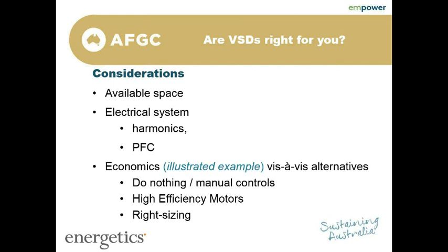If you're quite restricted on floor plate for your site, they do take up a little bit of room, so making sure that there's room for them to be installed. Another thing to consider with the available space is the temperature. Variable speed drives in really hot conditions can sometimes struggle performance-wise. So if you're dealing with temperatures above 40 degrees, that might be something to look into a bit further before you go ahead with that. Check if there's somewhere else to position it.